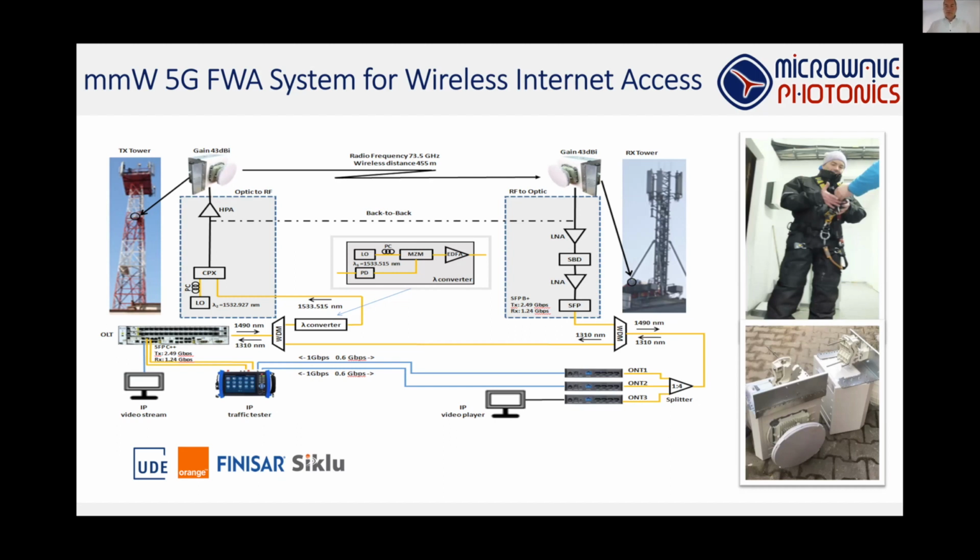What we do here is we are providing 5G fixed wireless access, so people can get wireless internet access using the conventional optical backhauling, which is in this case a GPON system. So basically you get access to a GPON system without fiber because we use a 5G fixed wireless access technology. So we bridge internet into your home using a wireless link, but this is at millimeter wave frequencies, which are foreseen for these fixed wireless applications.